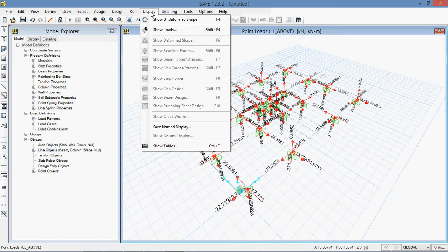So the sequence for the footing selection is first isolated, then combined, then strip or continuous footing, and then we go to the mat footing. And if the mat footing is failing in punching shear, we can provide beams or we can increase the thickness. And if with mat footing our design pressures are not achieved, then the last step is the pile footing. With pile we can increase the length of pile and achieve the required bearing capacity of the soil.